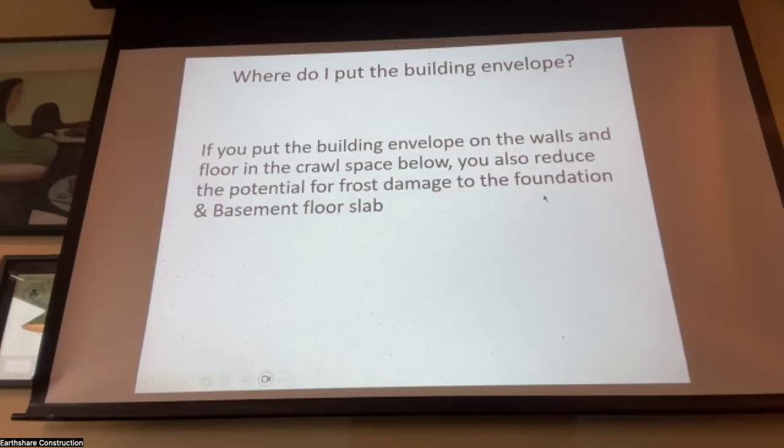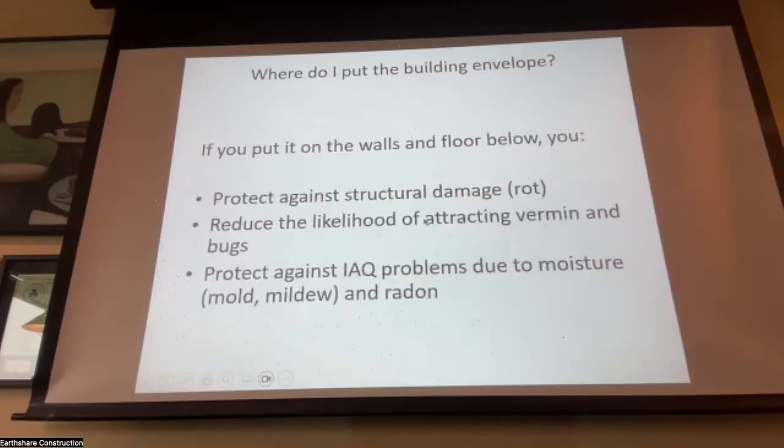And the foundation wall problem is generally more in rubble walls than it is in poured concrete walls. So they're a little more prone to frost action. We'll talk about that as we go.